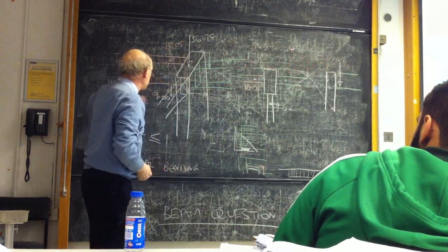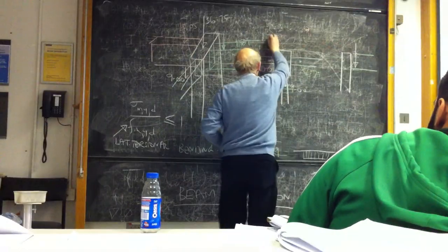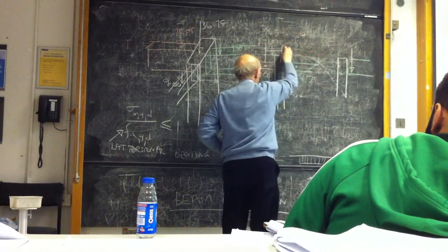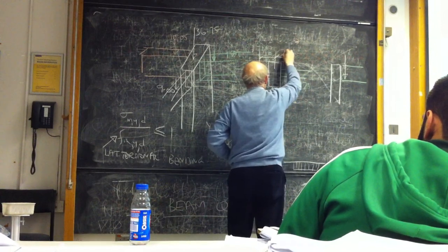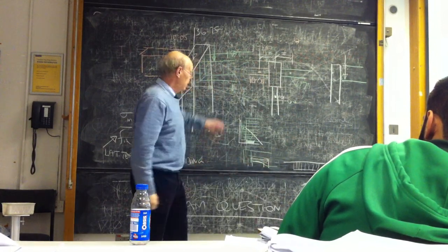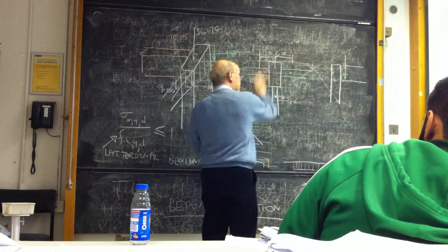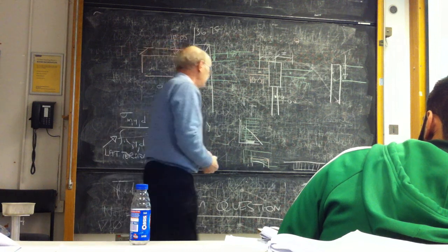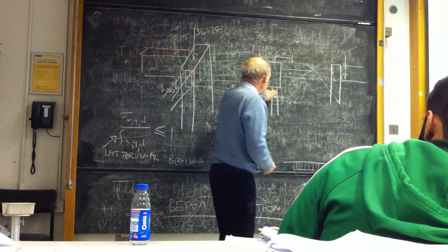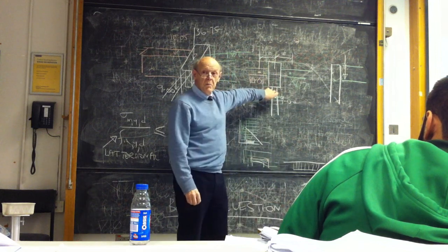Right. Now then, because these loads are unequal, even though these distances, that one and that one, even though those distances are equal because of the way it's built, because this load is bigger than this, there will be a bending moment in that direction about the z-axis, won't there? There will also be a bending moment due to this one about the y-axis. So there'll be biaxial bending.